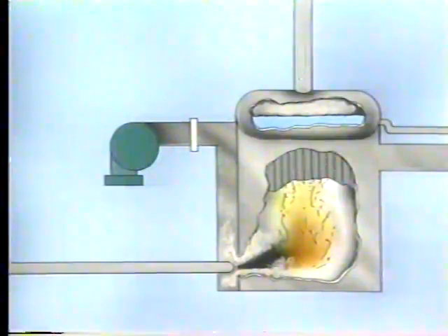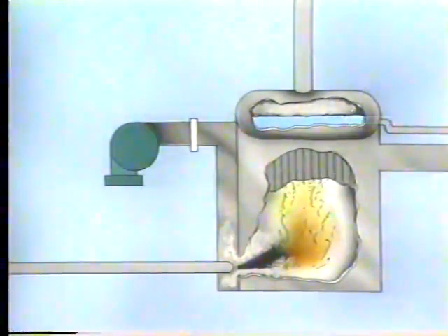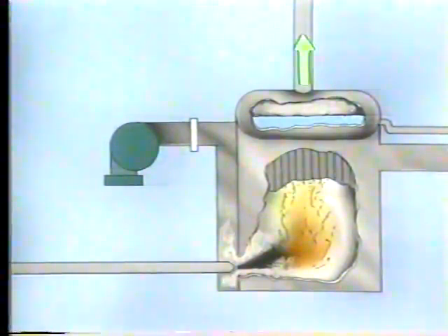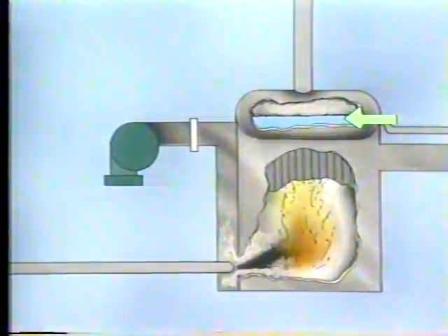The flow of steam out of the boiler must be able to satisfy the demand for steam in the plant. As the demand for steam changes, the amount of fuel and air needed in the furnace and the amount of water needed in the drum also change. In the system we're using, it's possible to monitor the steam flow out of the boiler to determine plant demand and use this demand to maintain the proper amount of heat in the boiler furnace and the proper water level in the boiler drum.